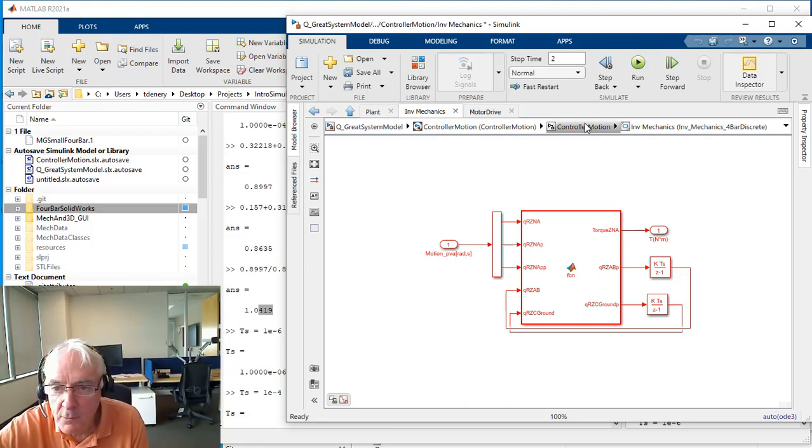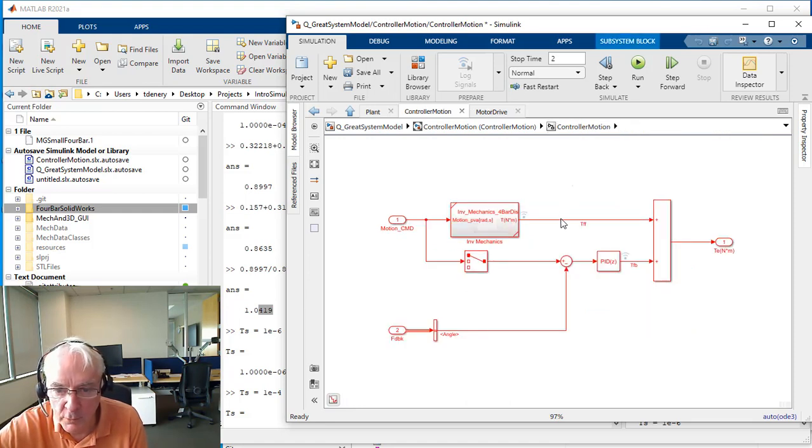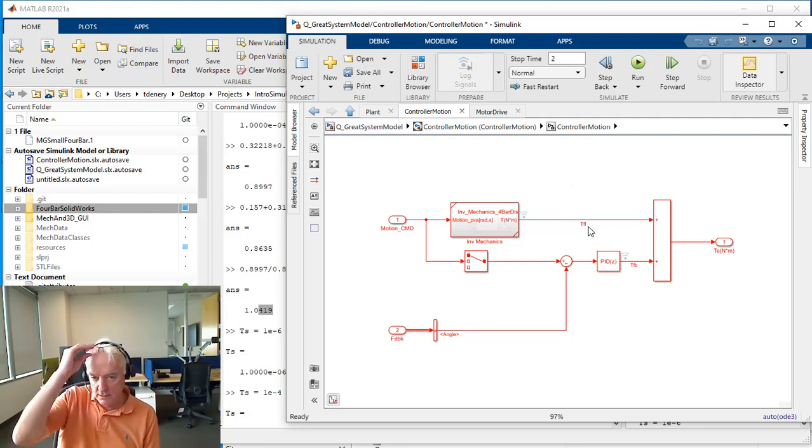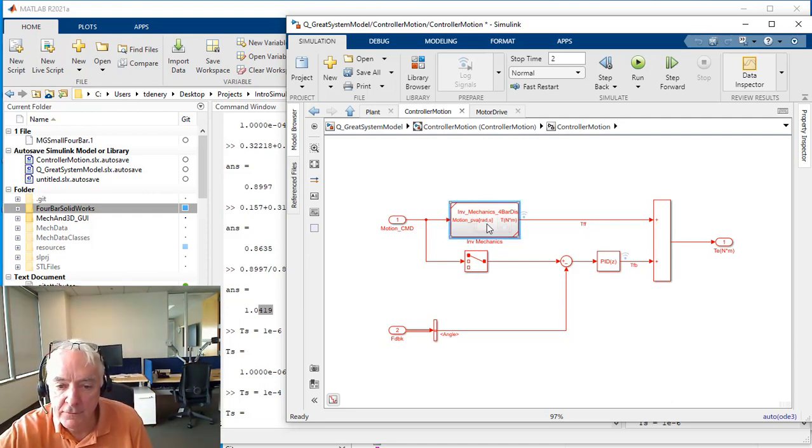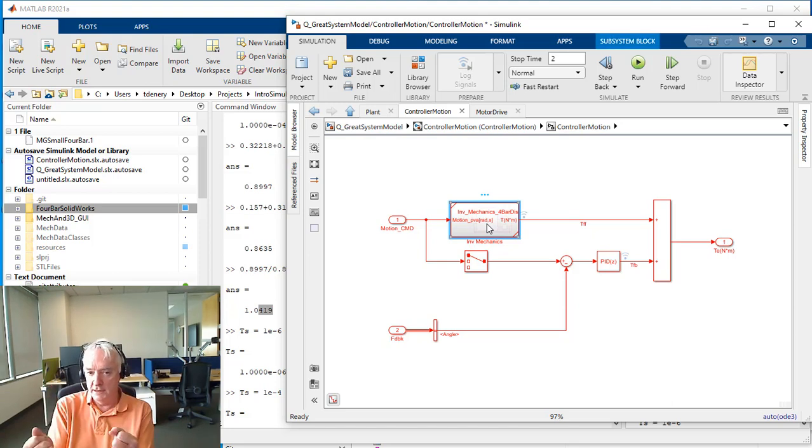What I wanted to get at is this idea that we presented in one of the earlier demos: the specifics of the control algorithm, a piece of it being feed forward and a piece of it being feedback, and the PID is a feedback. But the feed forward is essentially understanding your mechanics really well and representing it properly in your feed forward component. Well, if I'm going to switch to the CAD version and it's 4.2% heavier, I know that this feed forward piece is not going to be perfectly representing that anymore, right?